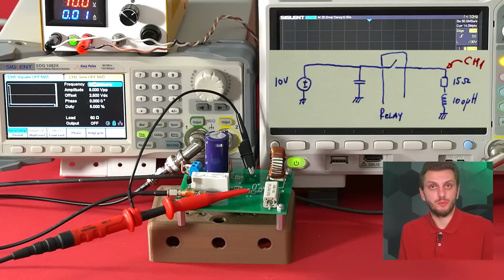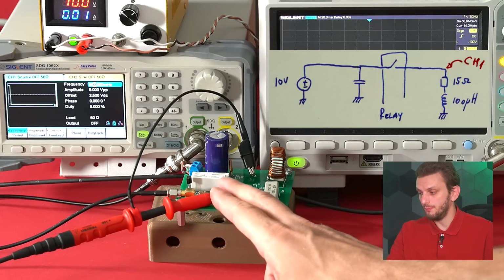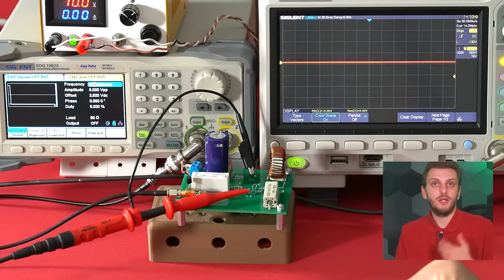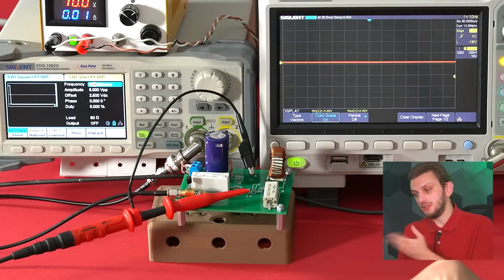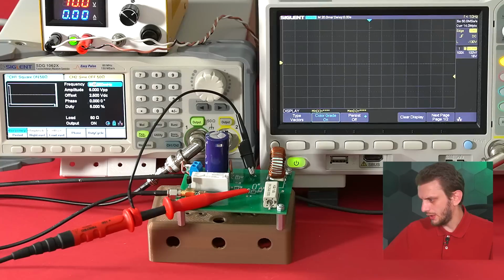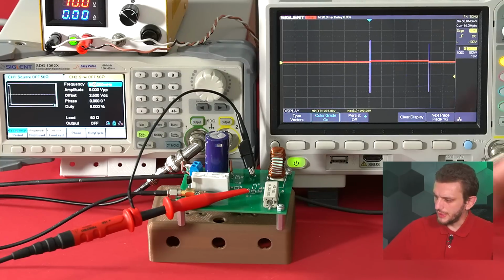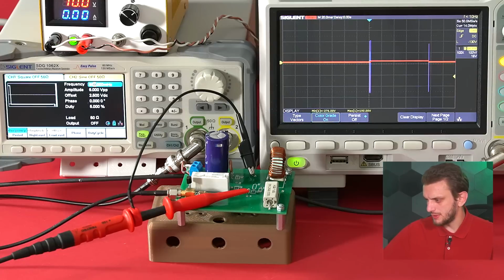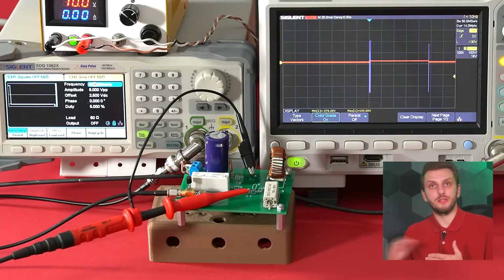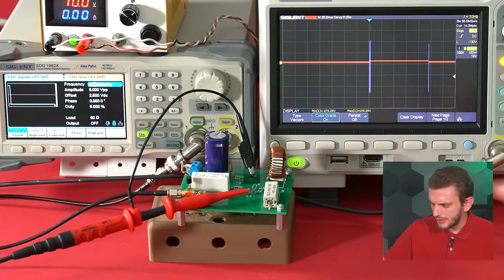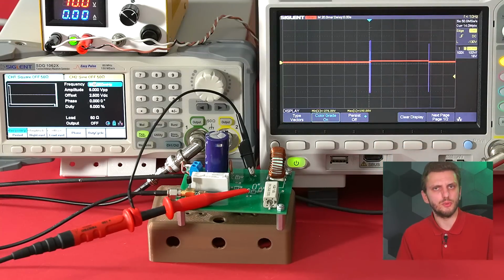And to be able to observe what's going on, I have my high voltage probe measuring the voltage that is present on the load. So the voltage that the contacts are seeing is the supply 10 volts minus whatever the probe is measuring. So if we run the circuit as is and just make a single capture, we can see that during both transitions of our switch we are getting some high voltage spikes. This is because the contacts are bouncing, they don't have a clean turn on, turn off transition. And the spikes are at 276 volts in this case, but they go up to around 300 something volts.